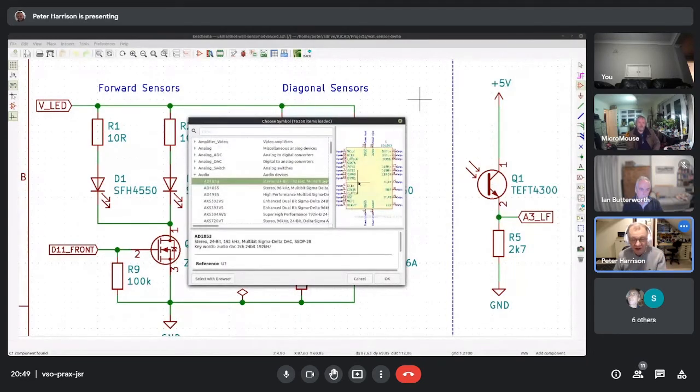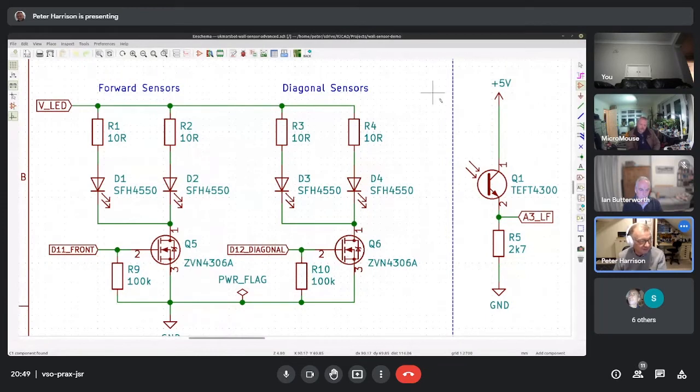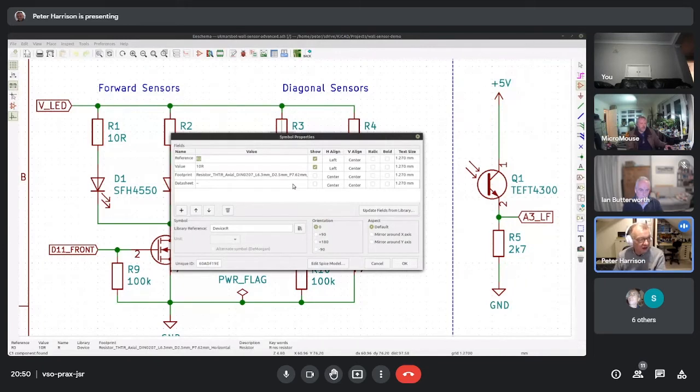I don't know. So, just as you might expect, you have components and footprints. Just remember that what you're putting in here is just a symbol. You can move stuff around. Lots of things have handy shortcut keys. You can hover over a component and hit E. Whoops, missed. Hit E for edit, and up will pop a dialog with all sorts of interesting things about it. Much easier than going off to a separate library manager.